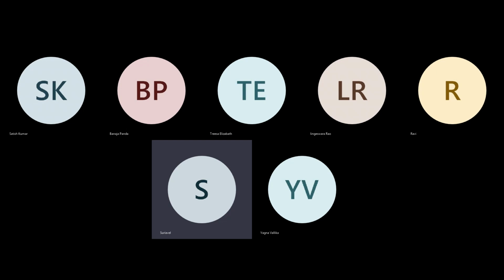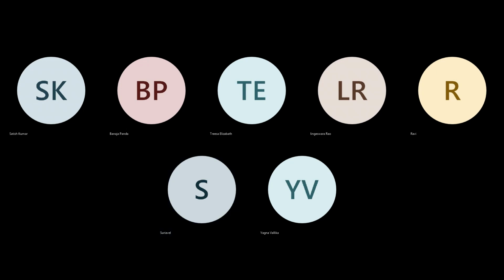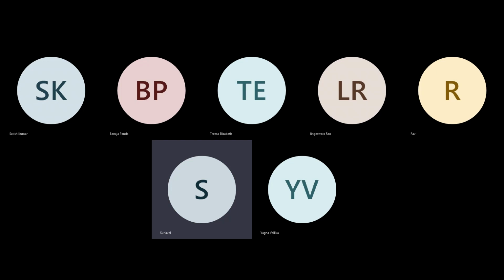There are situations where a design may have various such macro groups, and according to the given core area utilization, there is a possibility of notches at the end of the macro placement.